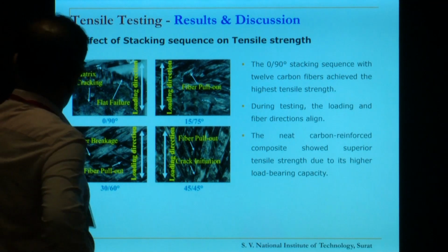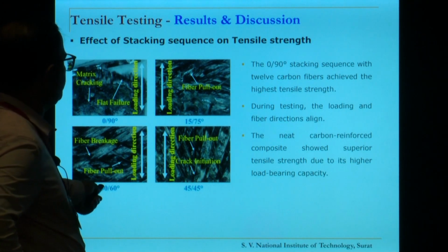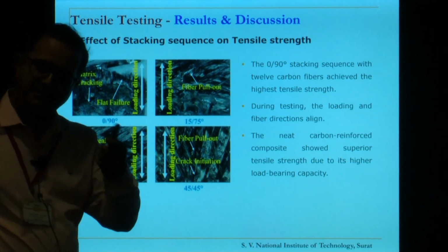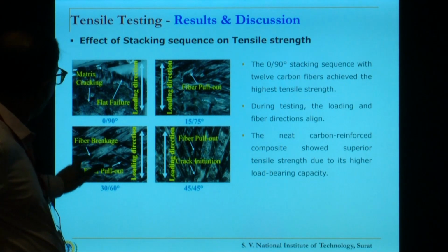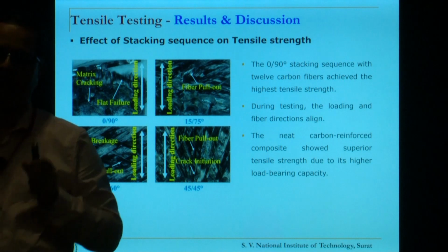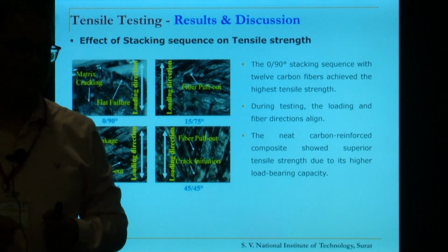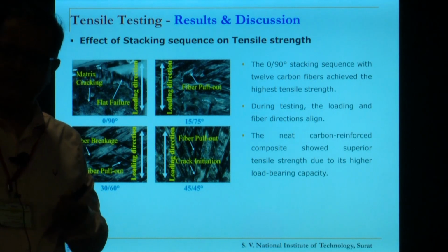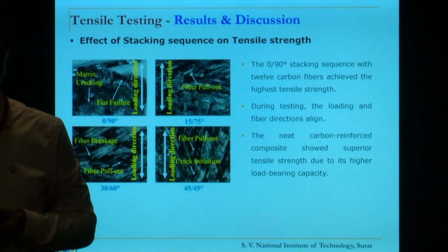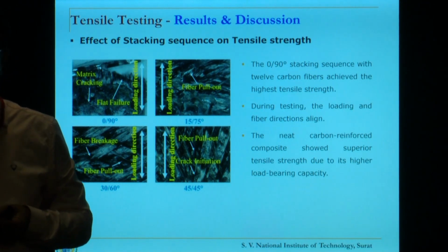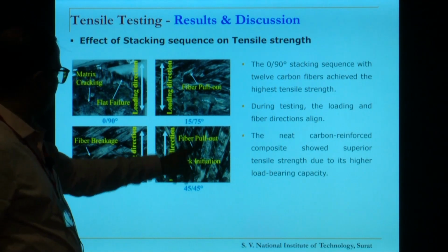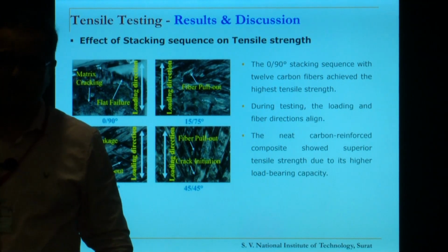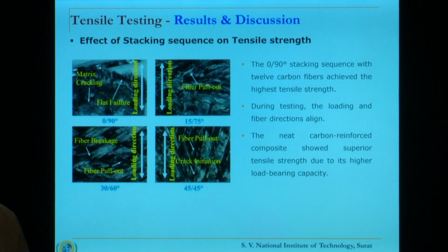So in many cases, at different other angles, probably this is carbon fiber, because carbon fiber exhibited the better strength. We went through all these observations and we saw how in all the cases there was fiber pull out. So the fiber remained intact, it did not break. At the most it got elongated and later on it got pulled out from the structure. It did not break, it got pulled out of it. That exhibited in all these orientations, and that is probably the reason that carbon fiber did not break easily. So it exhibited better strength.